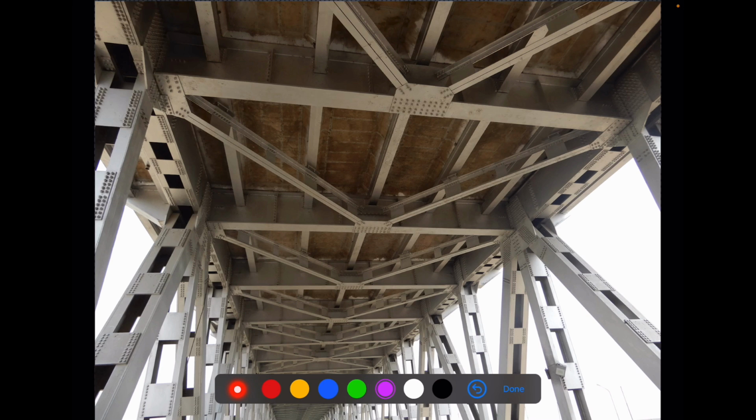Now we can clearly see the top arrangement of this rail cum road bridge. These are the sway girders, and these are the top lateral bracings, TLBs, and the two sway girders are also connected with an I section to provide better stability. All of this has been connected with this deck slab concrete.